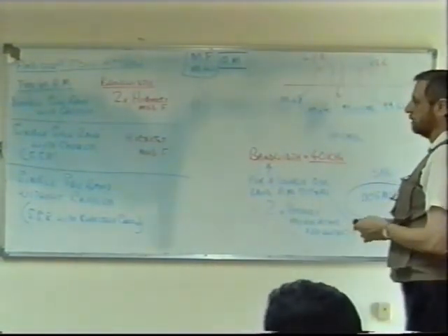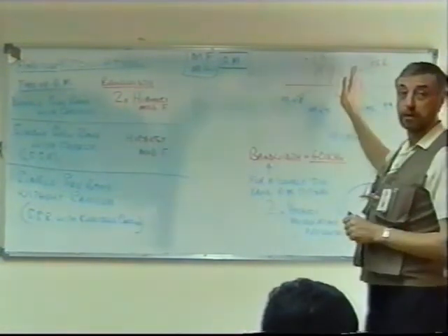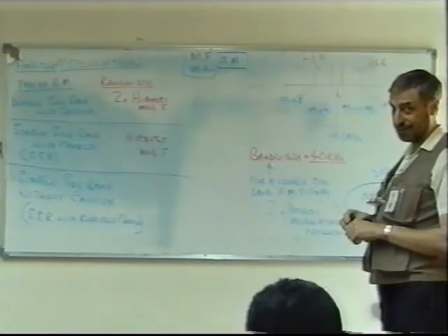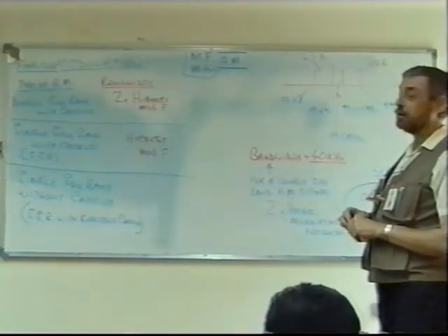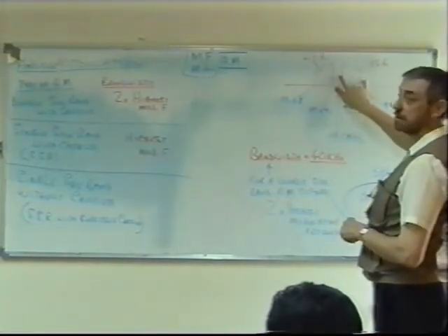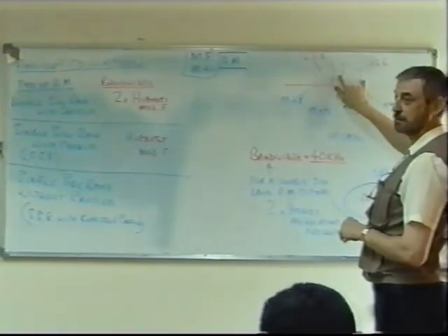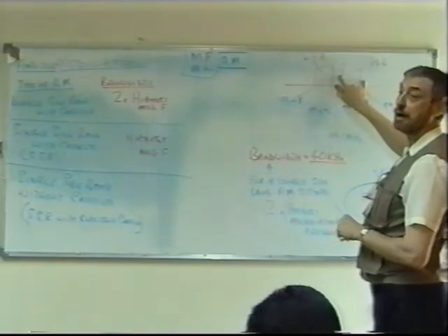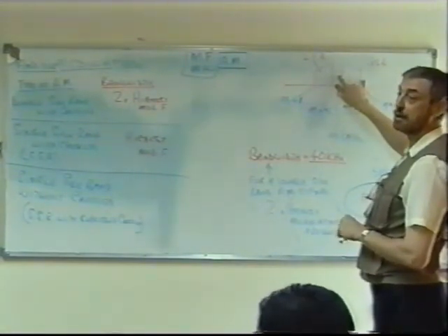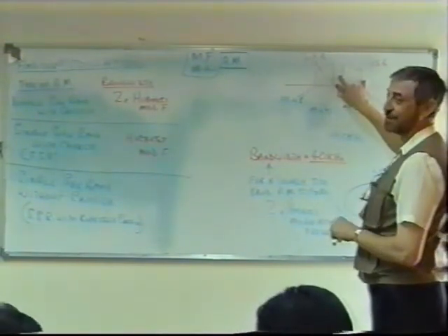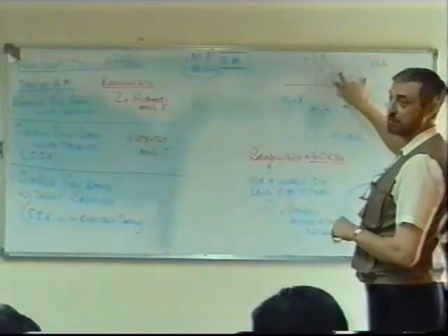What do you think the bandwidth will do? Is it going to change the bandwidth? No, there won't be any bandwidth. Oh yes, we're still transmitting a sideband. How are you transmitting it without any? There will be no lower or higher, the other side. No. We still transmit a sideband, but we suppress the carrier.